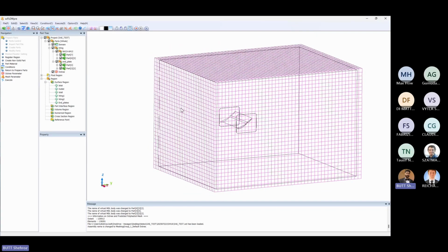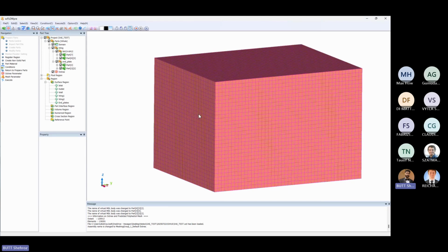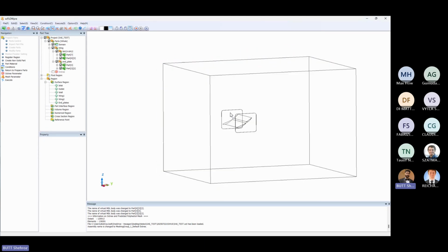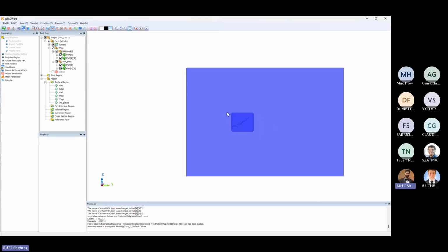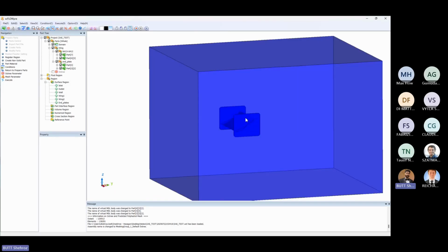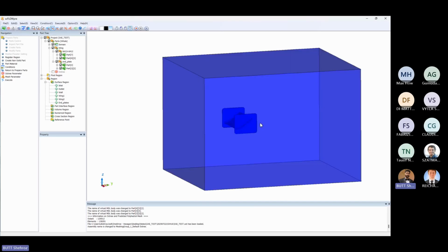But before doing that, there's a quick tip that I want to give you. As you may be aware, the flow at the outlet of the wing will be severely disturbed. And what we want to make sure is to capture this, what is called the wake region, very accurately. So at the moment, all the refinement we did was on the wing itself, but we don't have any refinement on this region. So what we can do is to register a volume region around the wing, and we can refine that one. So let me show you quickly how we can do this.